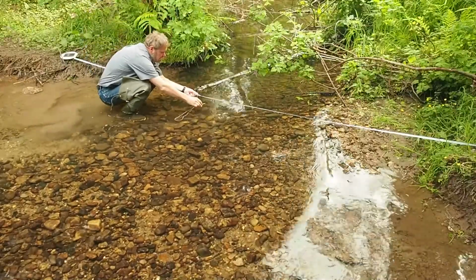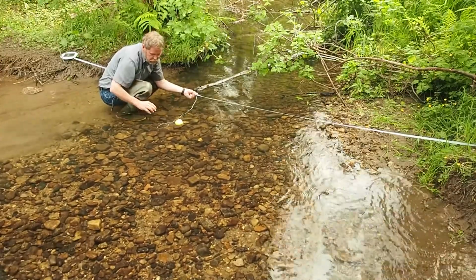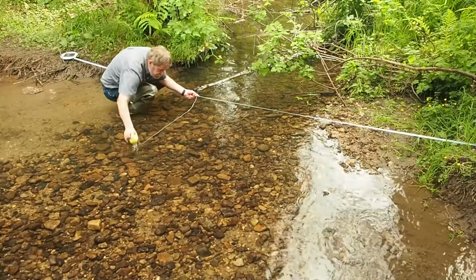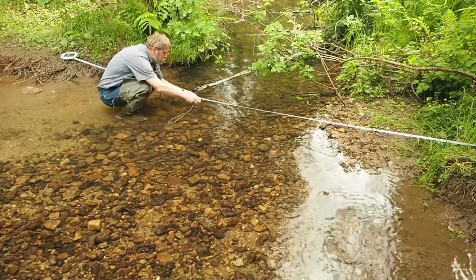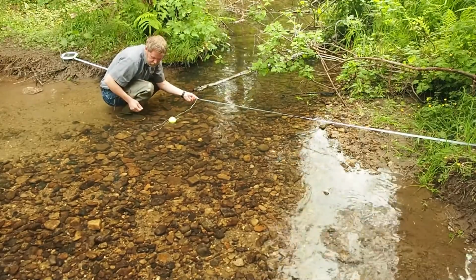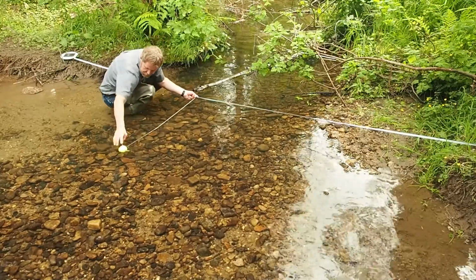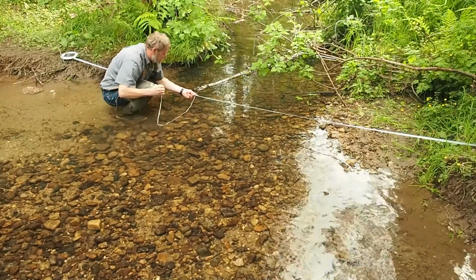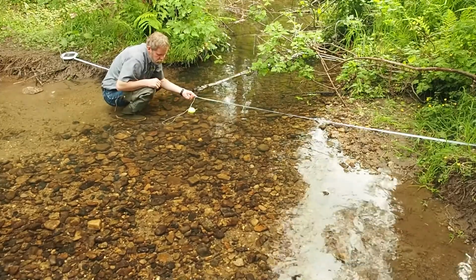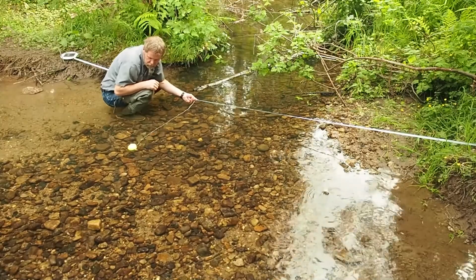IDAH2O measures velocity, or how fast the water is moving, using a tennis ball tied to a 1 meter long string. Highly technologically advanced, right? Well, it works, believe it or not. With your scribe standing ready with a stopwatch, float the tennis ball and hold the other end of the string right with the ball. Be sure your body is not affecting the stream flow where the tennis ball is. Release the ball when the person with the stopwatch says go, but keep the other end of the string that you're holding between your fingers still.